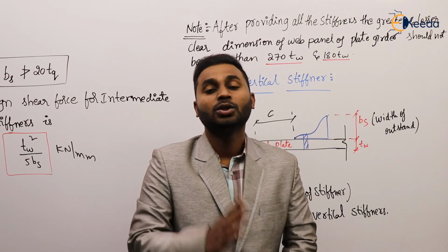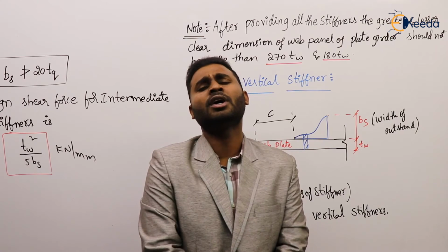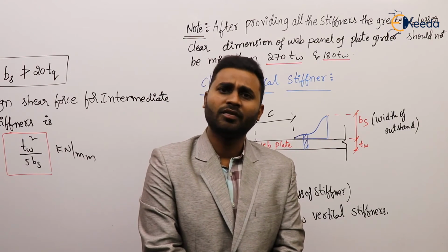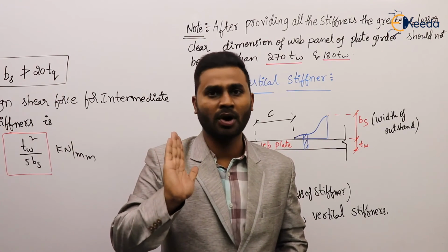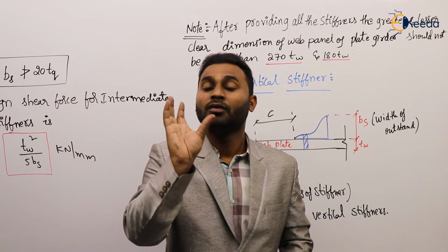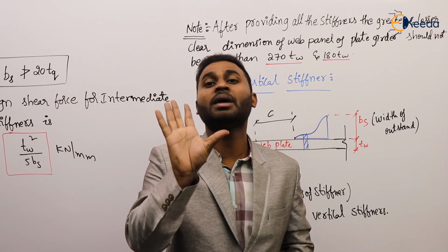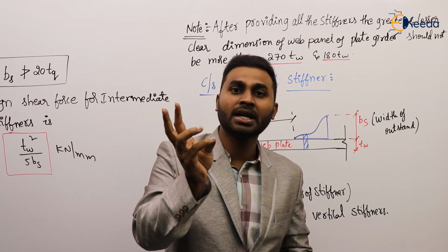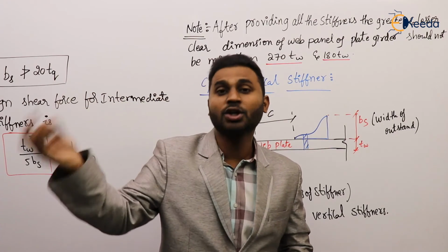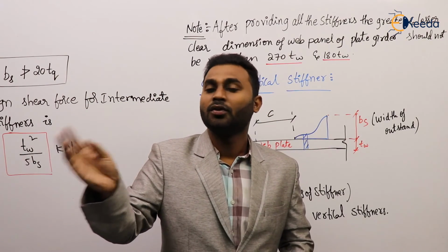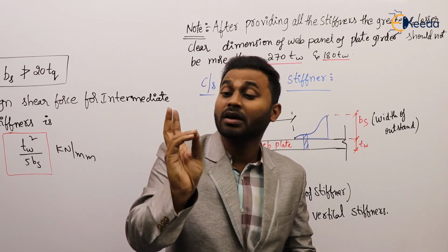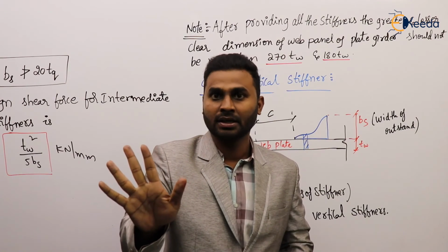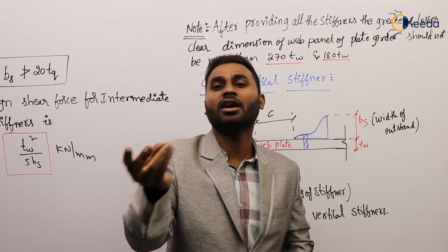Okay, at bridge. So whenever we are going to design a plate girder, obviously there exists a support and point load. So for sure, without any hesitation, we have to provide a bearing stiffener, be it end bearing or load bearing. In addition to that, we are not going to provide the intermediate stiffener in all the cases, like transverse stiffener or horizontal stiffener.